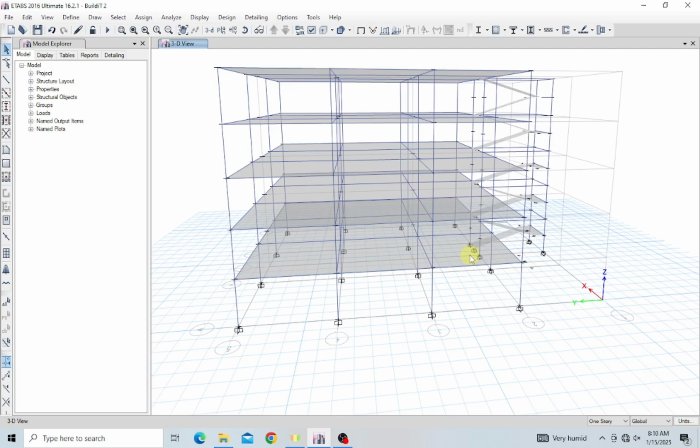It's not a structural element. It's just some wall-like structure we create around the building to facilitate or simulate the distribution of the lateral loads onto our vertical structures, or anything in the structure that is helping the building to resist or combat these lateral loads, like our column or our shear wall.